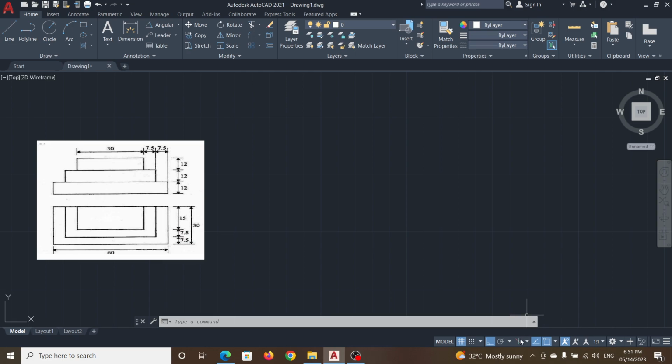So here let me now click on this isometric drawing. Okay, now you see isometric style. The cursor is converted into isometric style. So I will select the line command here. I select the line command, and please see that your ortho is on. Okay, the ortho mode is on, or you can press F8.